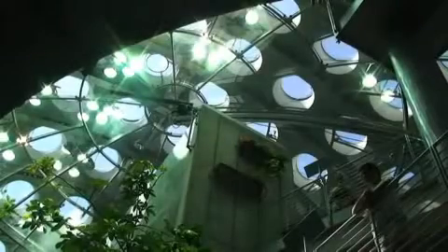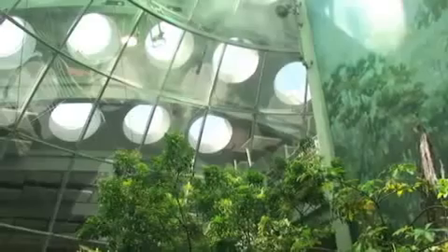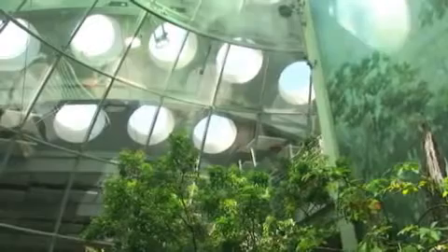So we had to find actually the exact diameter which would allow the diaphragm integrity to remain intact, but also flare out the bottom of the skylight to maximize the amount of luminance in the space. And you can see the actuator, which is connected to the building management system, which allows those skylights to be opened during periods of high heat buildup.